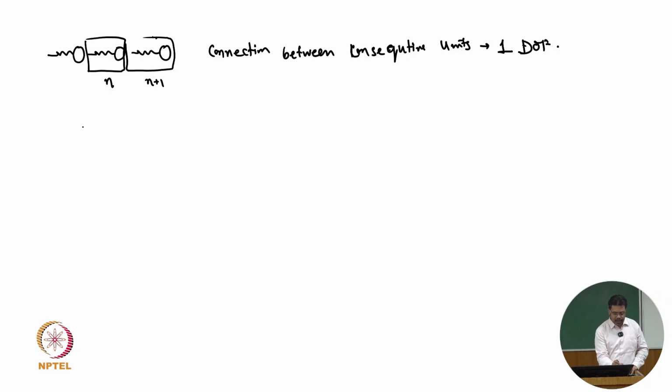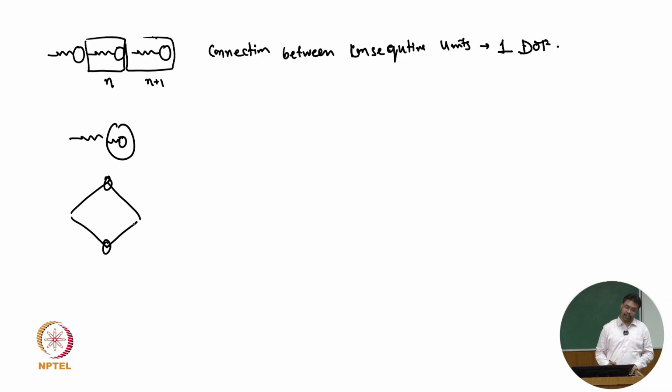Now here you may have your unit cell like this, that's a mass-in-mass unit cell. You may have a unit cell like this type. This is an inertial amplifier type unit cell. This may also be possible this way. So that may be an inertial amplifier, then you may add a spring in between. So that is the inertial amplifier, IA. This is your mass-in-mass. You may have a negative stiffness also.